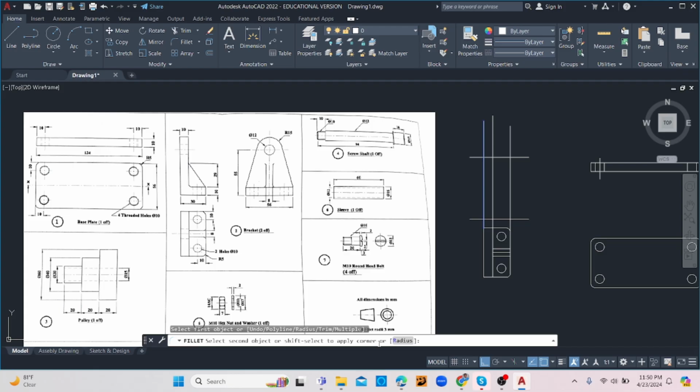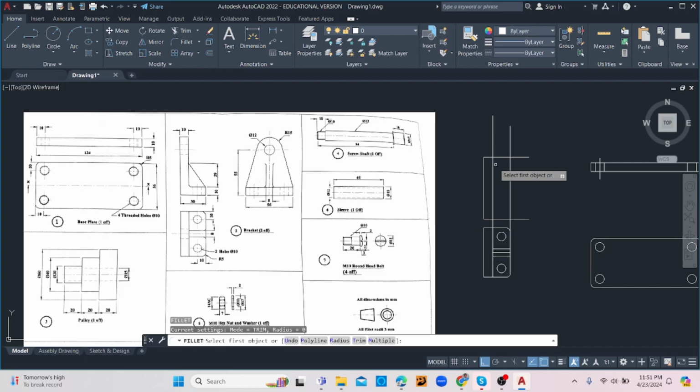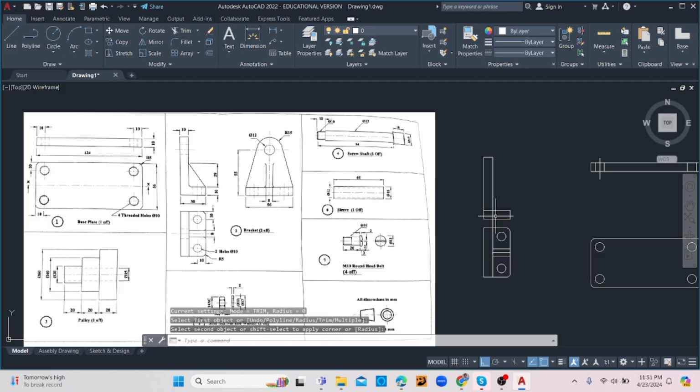Let me go ahead and change the radius back to 0 of my fillet. Alright, just like that. And at the top as well. I'm also going to do here as well. Now at the bottom here, the offset is also for that little portion here, which is basically 10 millimeters. So we can offset 10 as well up from the baseline here, and then we continue to fillet, trim, whatever method you choose, the corners. Alright, just like that, filleting the corners.